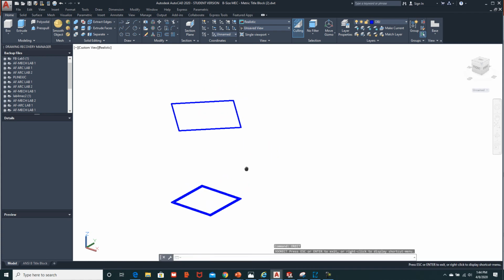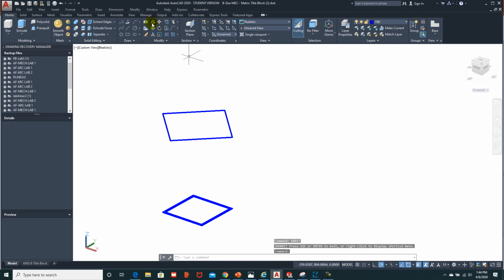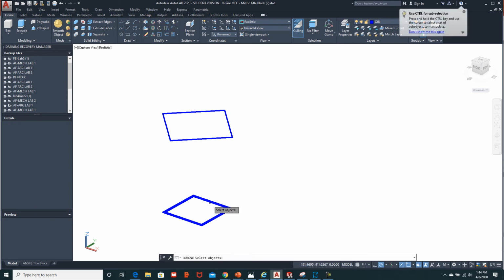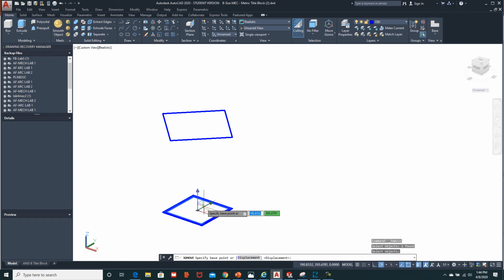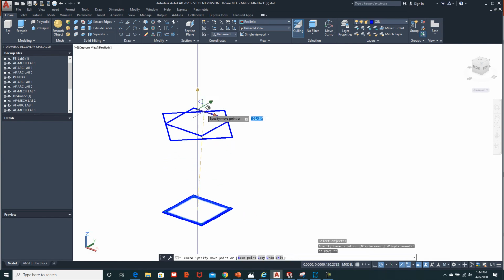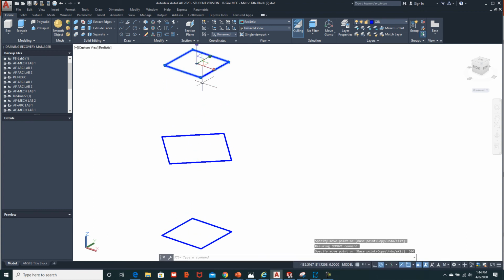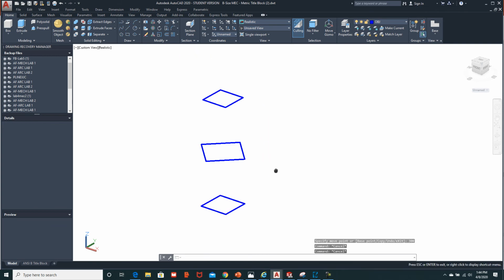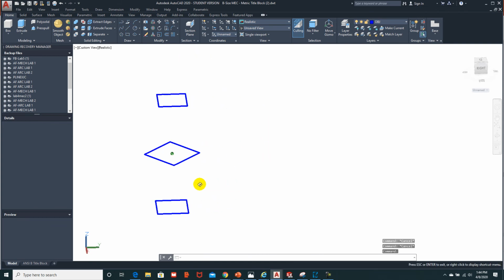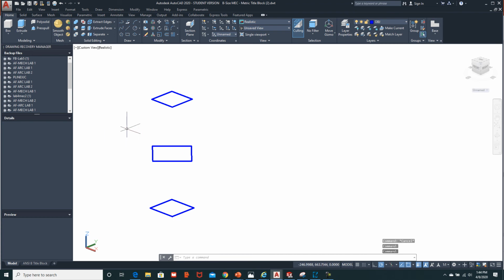And it's the same way. We'll go to the 3D Move command, we'll select that shape, we'll hit enter, we'll select the axes, and then we'll drag that up and we'll type 300. Hit escape. So that's our model that we're going to work with. And it's very similar to the same construction techniques that the author